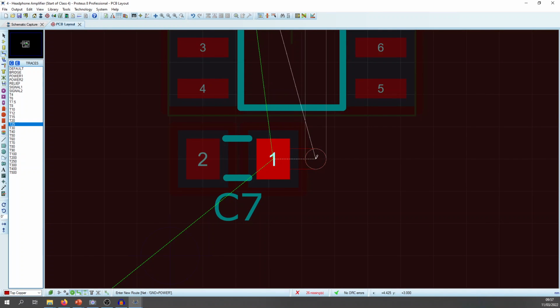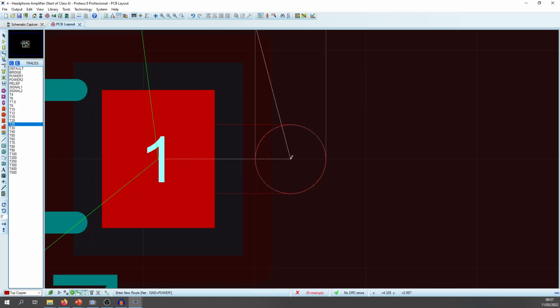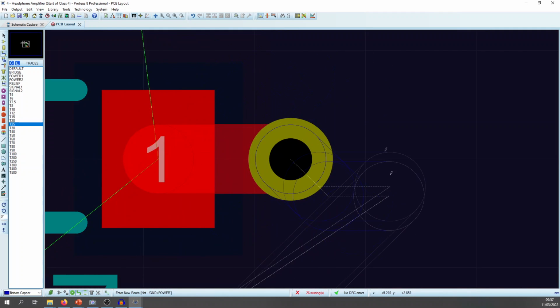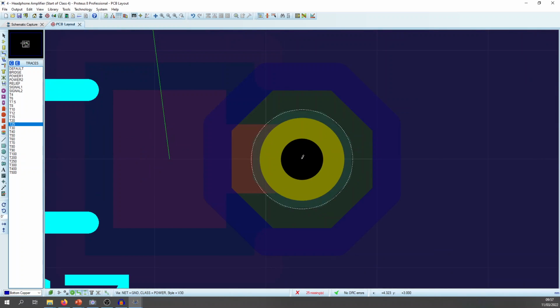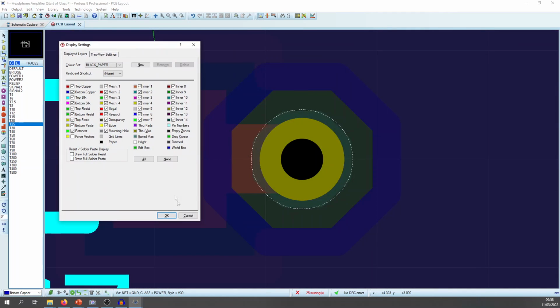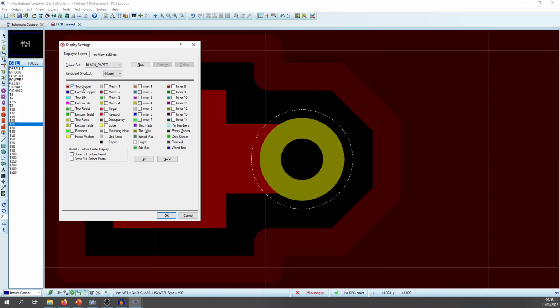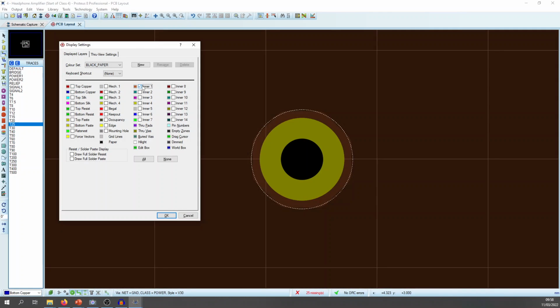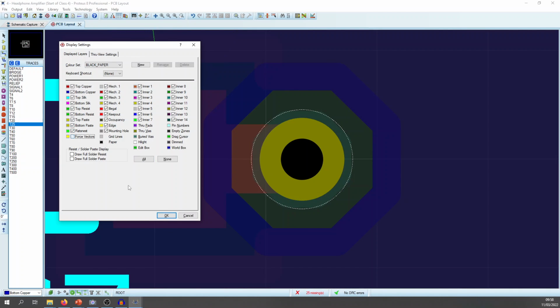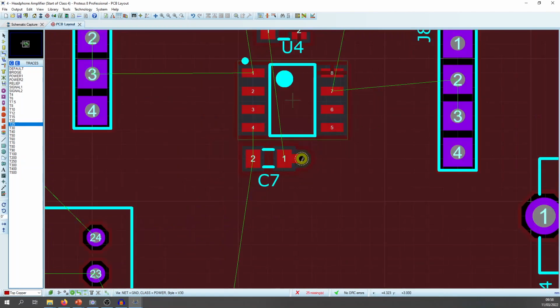I'm going to click to start making a trace, and then double click to place a wire. Now I'm on the bottom layer, and I've got this trace that's following me. If I right click to get rid of that, it just stops there. And what we can see is that wire, just as a quick demo, has connected not to the top layer, no connection, not to the bottom layer. It has connected to inner 1 because it's literally touching, and it has connected to inner 2. So the wire will automatically connect to those layers.